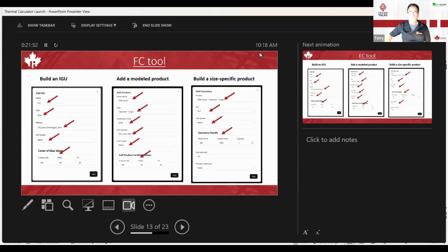So you can do obviously multiple products on a given project. A window tag, so W1, W2, D1, D2, etc. And then you can also create by elevation, which is a really unique feature. You can either do this in your setup; you would decide which way you want to go. And then you can create each elevation. So you can do solar heat gain based on a south or west or north or whatever, or you can do just the entire project as one complete project without elevations broken out. So a really interesting feature if you're working to try and manage your solar heat gain on specific elevations.